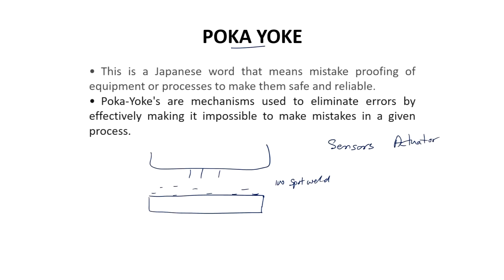So, what is required, and it is humanly not possible, with a production rate of every 2 minutes, every 3 minutes you are producing a car. So, it is not possible. What is required? Poka-yoke is required. You keep the sensors etcetera, unless all the components are there and all the components are at the right place, the jig will not come to do the spot weld.